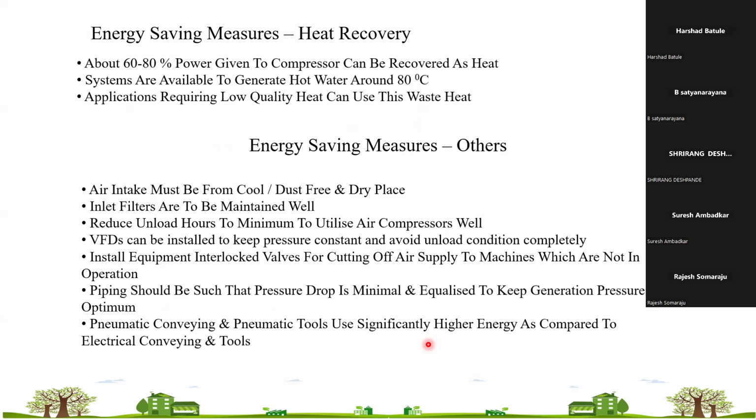That compressor goes into a load unload cycle. Your unload cycle should not be more than 30% of your entire cycles. Say it is continuously 50% load, 50% unload. Let's say 10 kilowatt is your load power and 3 kilowatt is your unload power.